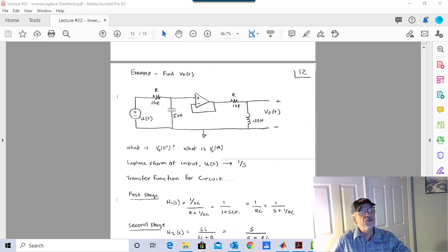Because there's no input current on this op-amp. So there's no current here. So I am not loading down this network. But out here, I'm going to have the same voltage, but I can put out whatever current I need. See that? That's why we call it a voltage buffer, because it's going to take this voltage here and just sniff it. It's not going to change. It's not going to affect the circuit because it's not taking any current. So I just call it a sniffing point.